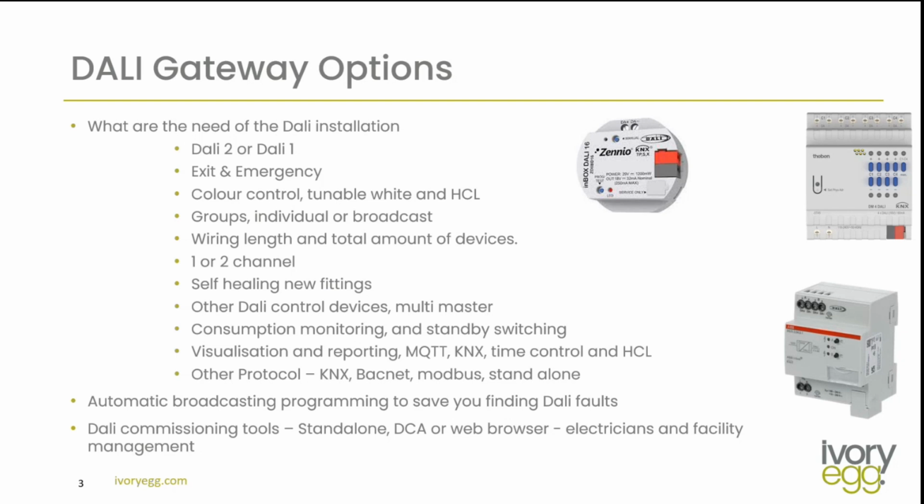And another big consideration when we're looking at DALI products is the DALI commissioning tool. What are the requirements going to be for that? Is the standalone tool going to be okay? Is the DCA app, which is an app that runs inside ETS, going to suffice? Will it need to be a web browser? Do you have to consider that there will be other people that are not trained that may need to access the DALI side for any kind of faults, replacing fittings and that? The type of people we're talking about is electricians and facility managers.